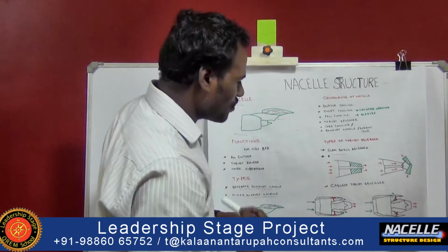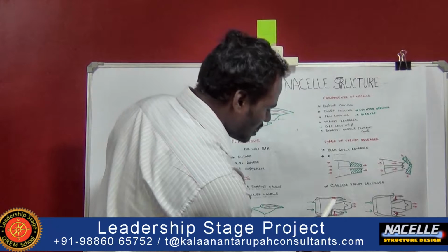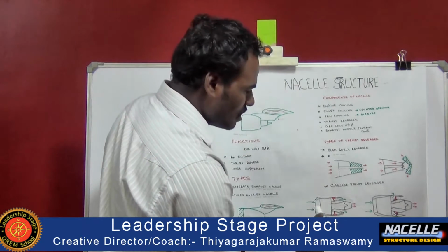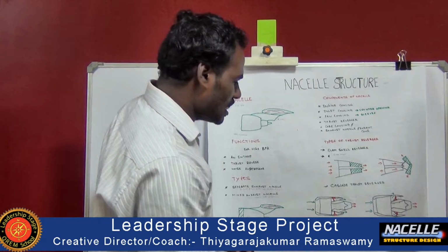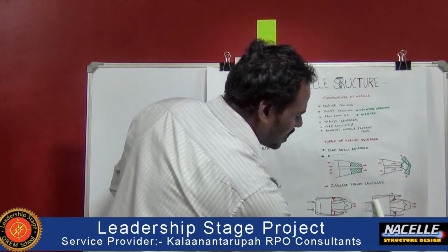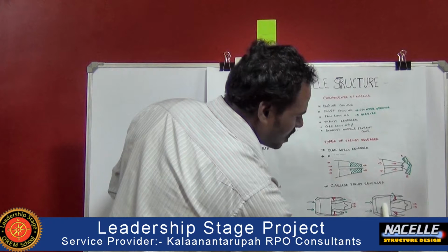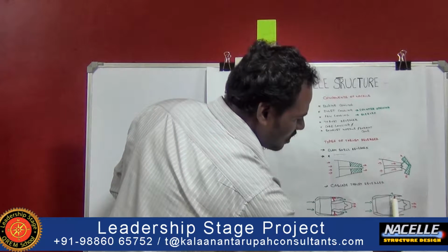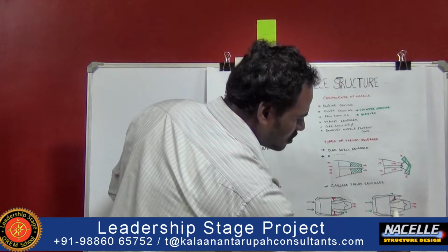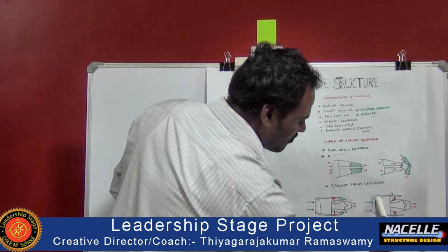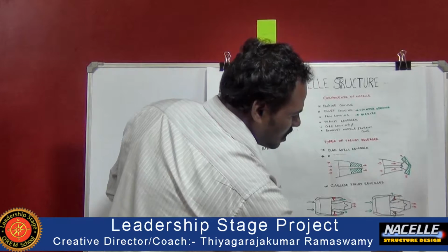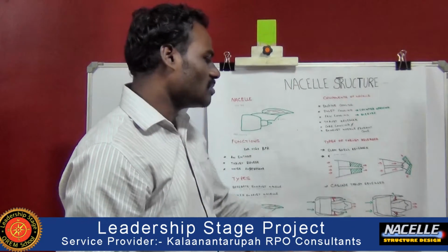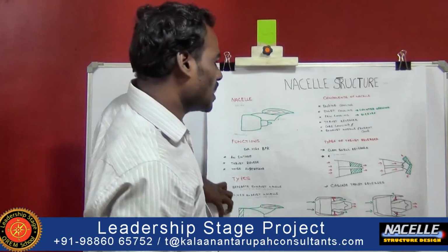In order to obtain thrust reverse, this valve helps us reverse the gas which is subjected into the engine. Here it shows the graphical representation of it. The air enters here. Then, in order to provide thrust reverse, this nozzle valve is closed with respect to the engine, so that the air which enters acts as a backward pressure in order to stop the aircraft with respect to the runway.